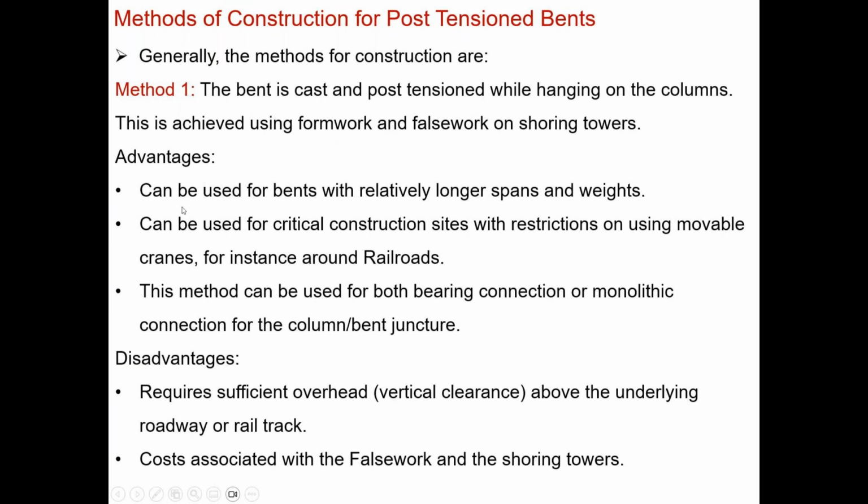The advantage of this procedure is that there is really no limitation for the span or the weight of the bent that you are dealing with. So it gives you more options to go to longer spans and heavier bents if you are casting it this way. It can also be used for construction sites where it's really critical to mobilize cranes or have cranes moving around to lift the bents or put them on the columns, such as those with railroads, which sometimes do not permit having movable cranes operating around the tracks during construction of the bridge.